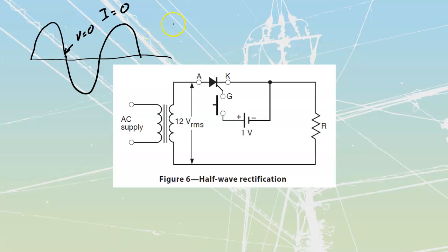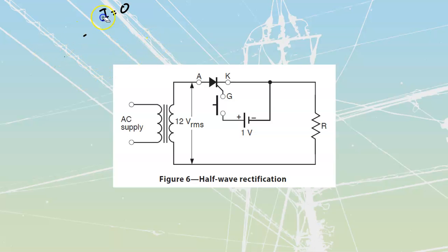So here we have a simple circuit that is now going to be inside of AC. First of all, I'm going to remove the SCR controller. We're going to look at this thing as if it were just a diode. If this was just a diode, we would know that the diode only conducts anytime that my anode is positive and my cathode is negative. So anytime that my AC is positive here and negative here, we would have conduction through here. Current would be able to travel through the resistive path and all the way back up.